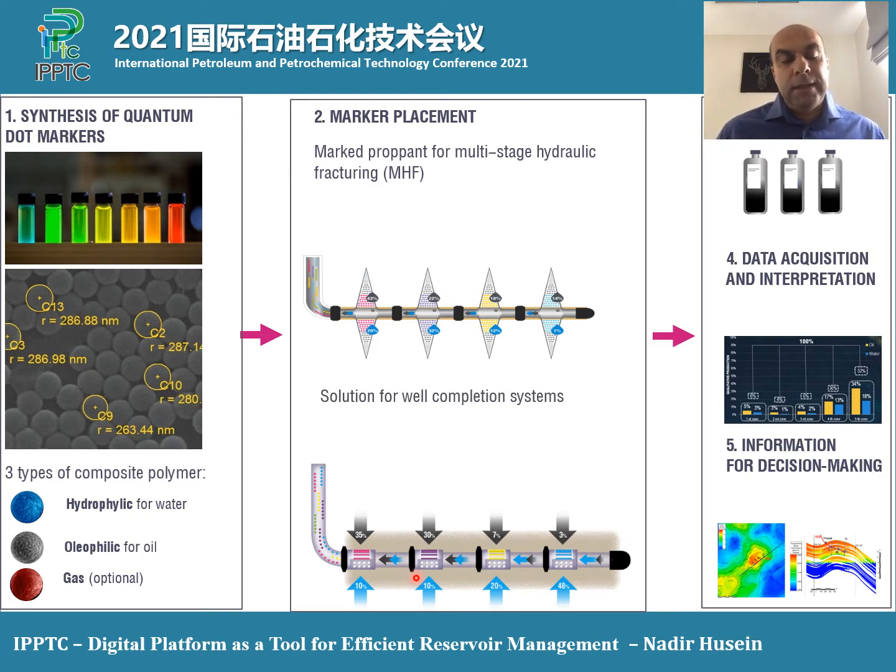Another method is placing traces in downhole completions, typically in open hole completions which have swellable packers, like multi-stage frac, ICD, ICV, or sand screen type completions, where the traces are put in very elastic material, wrapped around typically a blank pipe, and then protected by shrouds. And again, once the reservoir fluid is passing through the downhole completion, it releases the traces. The traces travel to the surface where they are captured and analyzed.